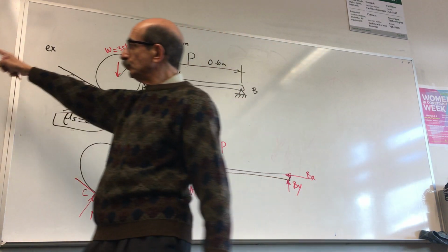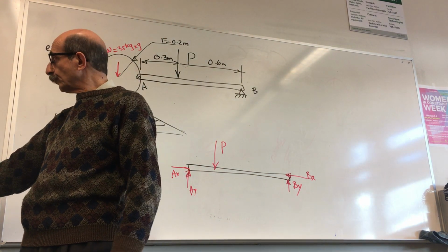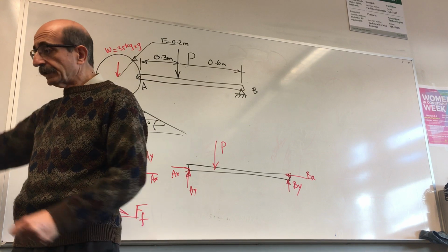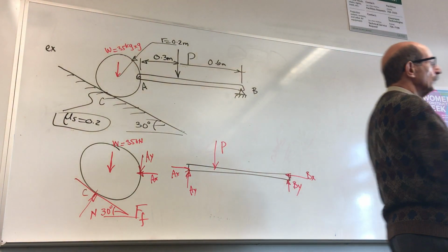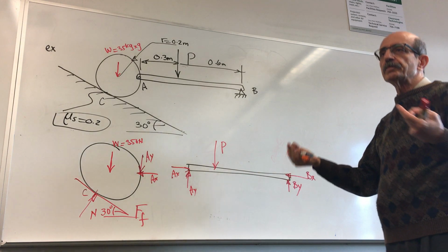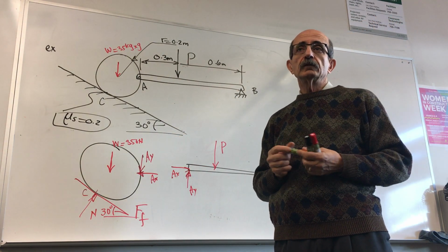So you drew a free body diagram, and you considered what direction each force will have. Then the last thing is you need to find the unknowns, but do not worry about finding all the unknowns. That's the biggest difference between frames and friction problems.